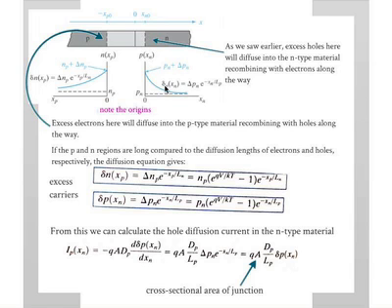Okay? Now, the same thing happens for the electrons. So you can write Np plus delta Np. Np is just the minority carrier concentration of electrons within this P-type material. Delta Np is just the excess electrons that have been injected across. And it also shows an exponential decrease where the speed of this decrease is proportional to the diffusion length of the electrons. Okay? In this case, note the origins. Origins are at the edge of the depletion region, not at the junction itself. So it's just shifted. But the picture is the same.